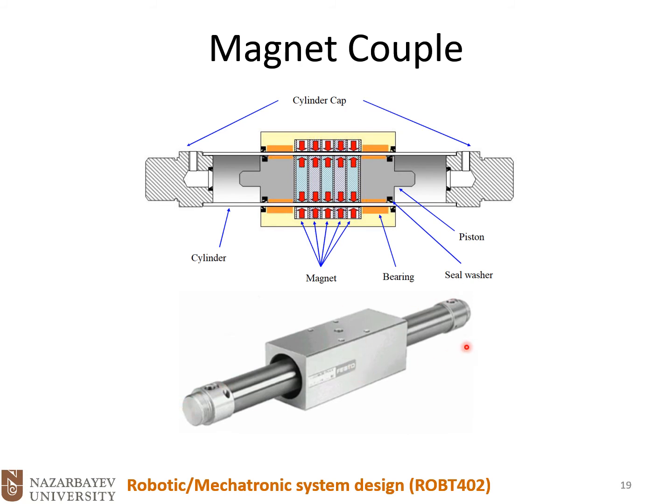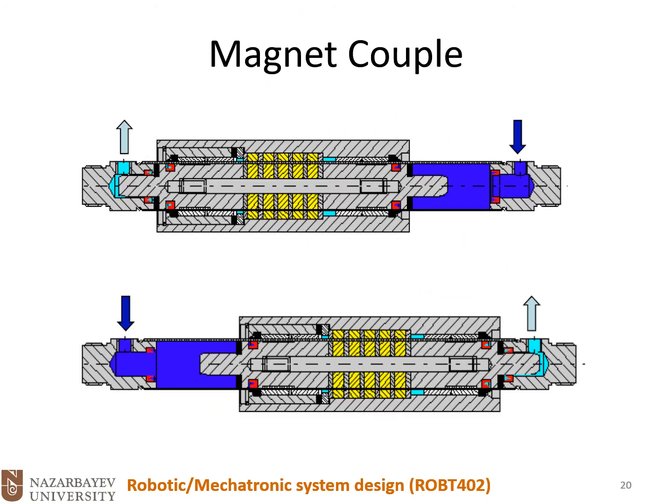So here you could see one type of these pneumatic cylinders, and you could find it on an MPS 500 on the testing station for the elevator. So the elevator is a rodless cylinder, magnetic, with a magnetic couple. Here again, you see this magnet coupling moving forward and backward. They have a piston and we have an external carriage, and you see the magnetic coupling between these two.